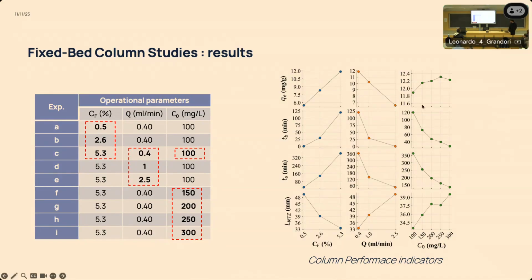Here, the adsorption capacity, which is the QE, is significantly lesser than our batch. Now, since this is a column setting and there is less contact time, as a result, our adsorption capacity decreases from 50 to 11 microgram per liter. And as the concentration increases, we have this kind of saturation happening where we can no longer adsorb more contaminant.